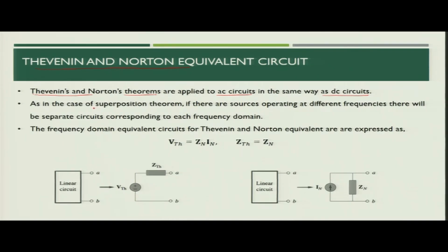Now, in case of superposition theorem we discussed that if there are sources with different frequencies, we need to create the separate circuits corresponding to each frequency domain and then process the information. So, in this case we will also create the different circuits for different frequencies and then finally we will use the superposition theorem to solve the circuit.